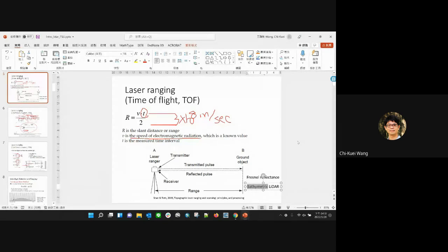So the transparency affects the efficiency of the LiDAR measuring the water depths. Apparently, the clearer the water, the better the transparency, the better the efficiency this LiDAR has. But just so you know, bathymetry LiDAR is more for coastal application. You don't use it for open ocean. You just use it for coastal areas where it is dangerous for a ship to get to.